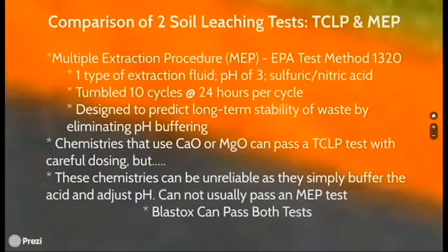Now, as I alluded to earlier, you can achieve a pass on the TCLP test. However, it does require some very careful dosing. And in the field, because things might not be as precise as in a lab, you have to be very careful about how you do that, because if you add too much, you could actually cause the materials to leach at a higher rate than before you added anything.